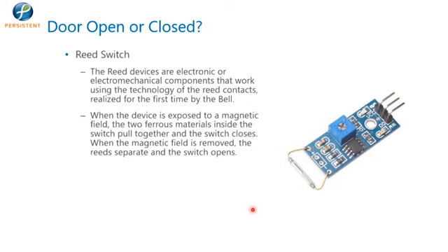So, you can just take a sample POC here. If this reed switch is connected to a door and I want to control the sensing of whether the door is open or closed, then depending on the magnetic actuation, with the magnetic field coming near here, I would say that it is in a closed position. So, I will conclude the door is closed. If it is taken away, that means the door is getting opened. In that case, the magnetic field is off.